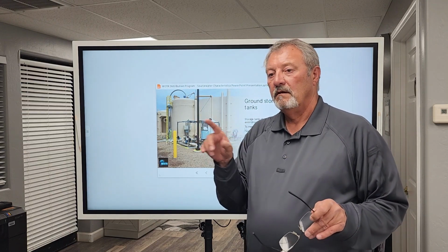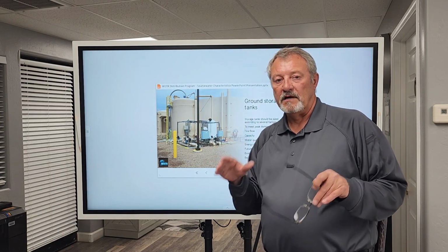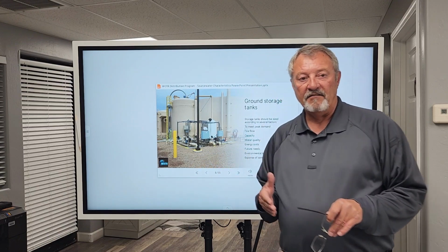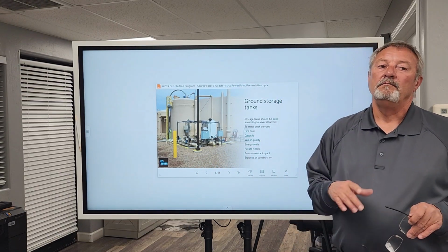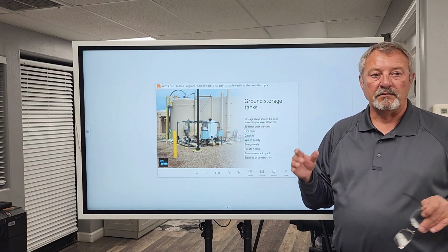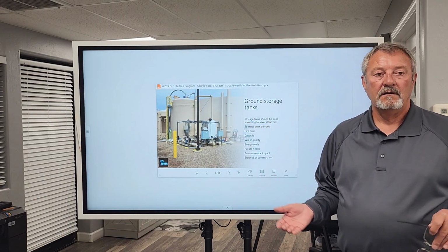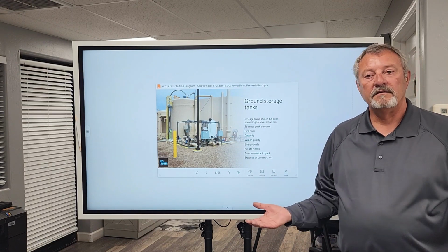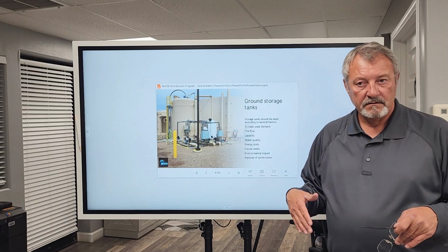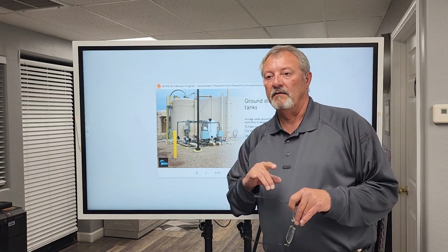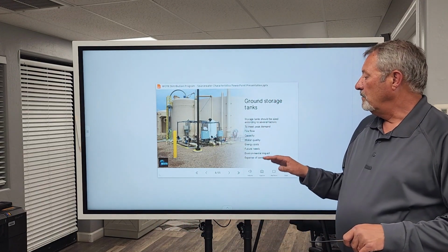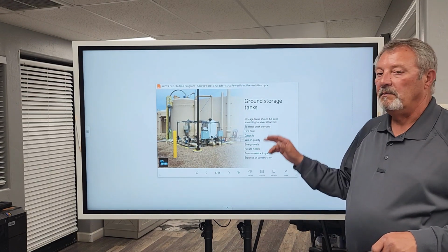So the morning peak, 5 a.m. to 10 a.m., drops off, it passes. When we get into 5 p.m. to 10 p.m., peak demand comes up again. People are coming home from school and work. They're doing their laundry, they're cooking dinner, maybe taking showers, they're doing whatever they're doing, but it's using water. So we have 2 cycles per day of peak demand, generally between 5 a.m. and 10 a.m., 5 p.m. and 10 p.m.